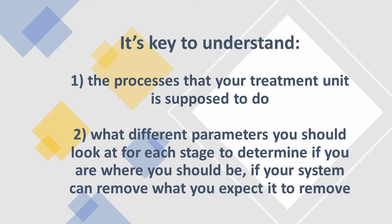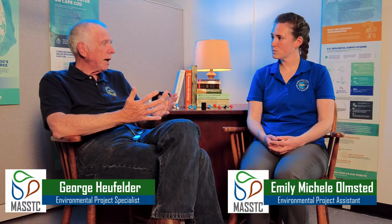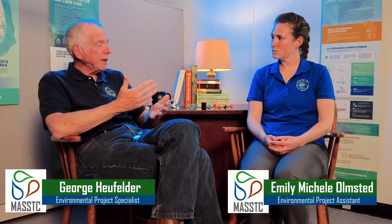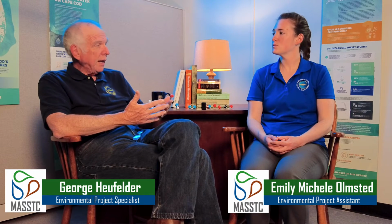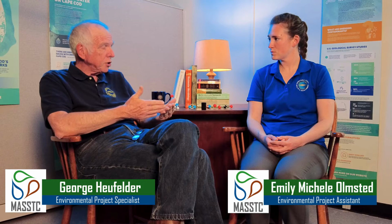Am I where I should be in order to have a situation conducive to removing what I'm trying to remove? And then with nitrogen, it's a pretty simple thing. You have ammonia coming out of an oxygen unit. It gets nitrified, and that you need a lot of air for. So you might take an intermediate measurement in that aeration chamber.